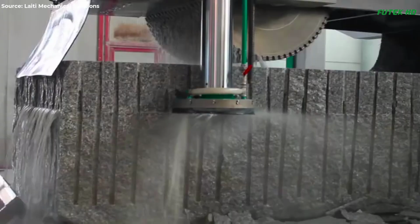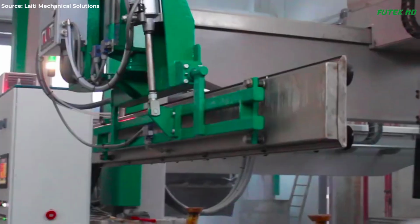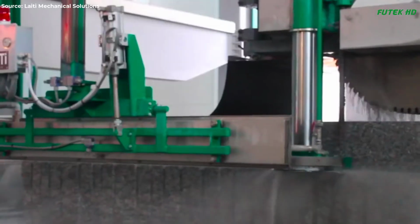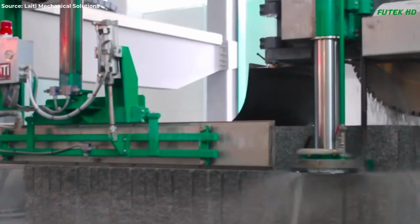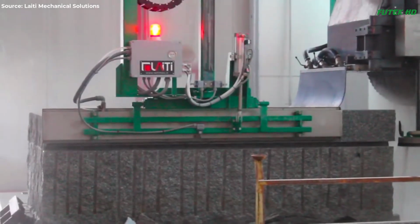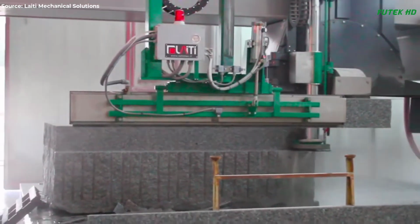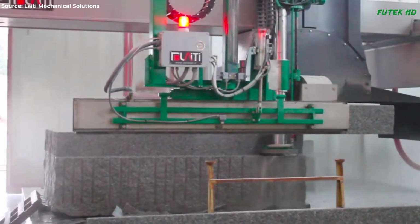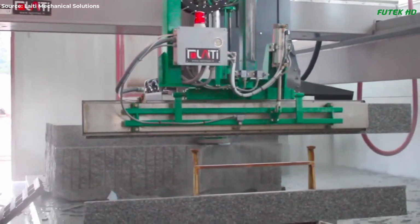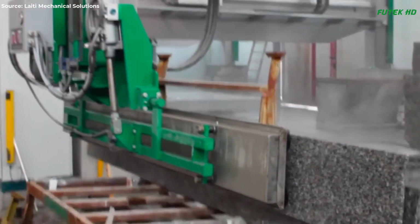Lateral displacement is managed with inverter-controlled precision gearing, moving on calibrated rollers in an oil bath protected by thermo-welded bellows. The cutter's mechanical and electronic components are of the highest quality. It is designed for easy maintenance, with fast access to parts requiring repair or lubrication. To maximize engine life in the corrosive granite cutting environment, the entire structure undergoes sandblasting followed by the application of a thick epoxy primer and epoxy enamel, ensuring robustness and longevity.